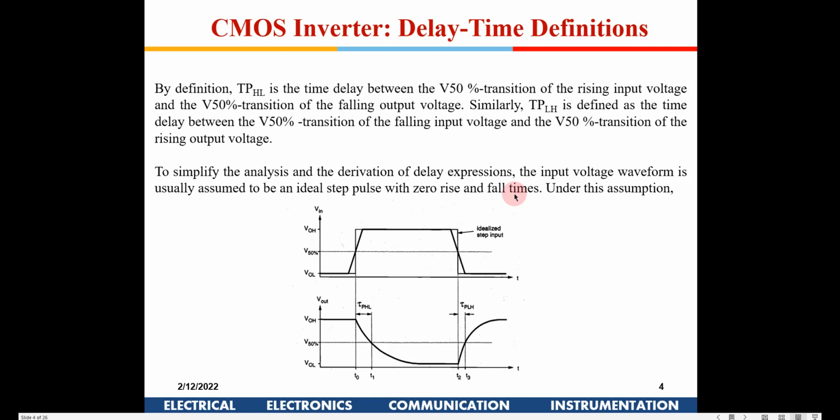So when you design a circuit, you do this 3 by 3 by 3 matrix. What it means is you will test the circuit with normal MOSFETs, slow MOSFETs, and fast MOSFETs. Also you will do it for VDD at 90% and 110%, that means 10% VDD variations, and then you will do it for temperature also, at room temperature as well as at 0 degrees and 100 degrees.